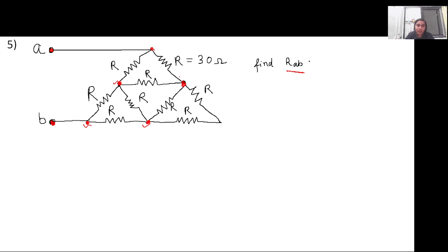So for the very first step, since we have to calculate the voltage across these two particular branches, what we see is this particular resistance and this particular resistance are connected in series, right? Because nothing is connected at this particular node. This entire branch is a single branch in which two resistances are connected in series, right? So first let us simplify those parts of the circuit which can be simplified easily. We'll keep the rest of the circuit as it is.